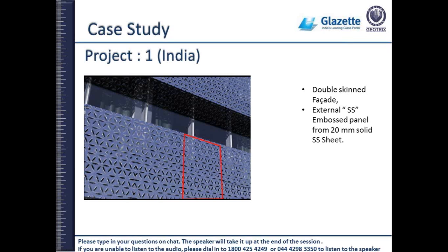I'm not talking about in general, I'm just talking about mainly most of the buildings are done this way. And you will not be surprised to hear a facade contractor will be brought on board once the structure is 100% finished. So what he does, he will check the building, he will find he needs to modify the system, he needs to modify the bracket because the slab is out, the concrete is out. So there are a lot of factors.